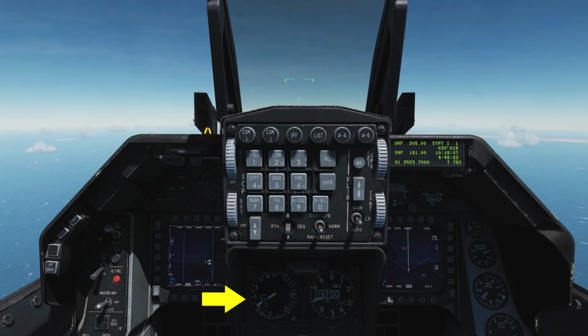The airspeed and Mach indicator is pneumatically powered by the pitot-static system. Airspeed is indicated by the outside gauge and pointer between 80 and 850 knots, and Mach is indicated by the window near the top of the indicator between 0.5 and 2.2 Mach. The red triangle in the indicator indicates the VNE, or velocity never exceed, and the green triangle can be set by the knob. The altimeter is servo-pneumatic and can indicate altitudes between -1,000 and +80,000 feet. It has both a primary electrically powered mode and a secondary pneumatic mode. If in secondary mode, the pneumatic flag appears on the gauge to indicate pneumatic mode.